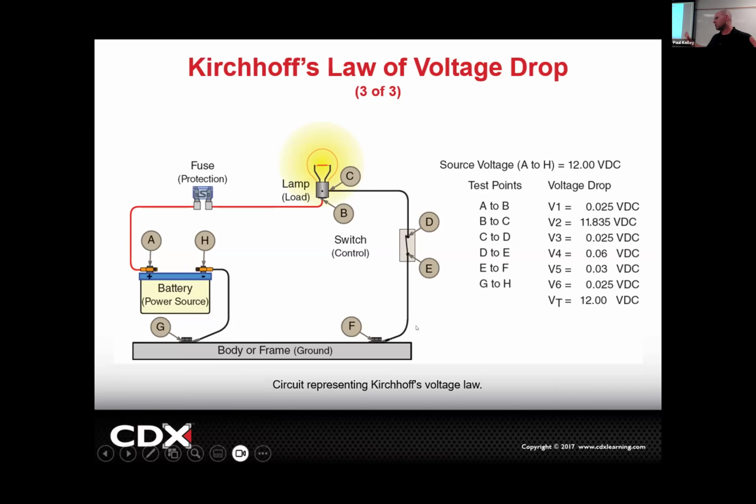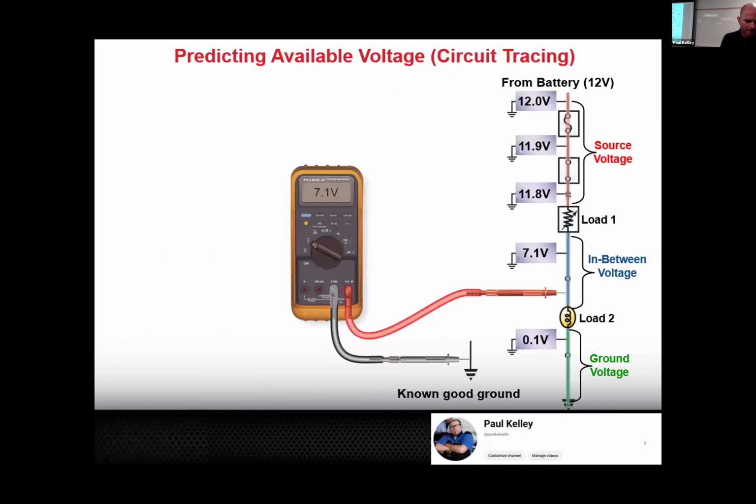So at least I've split the circuit in half, and I know if I'm looking towards the front of the car or towards the back of the car, and just systematically diagnosing it, right? So this is what I would personally do. If you voltage dropped each of these and found incorrect voltage drop, I would switch over to the available voltage. I would predict the available voltage.